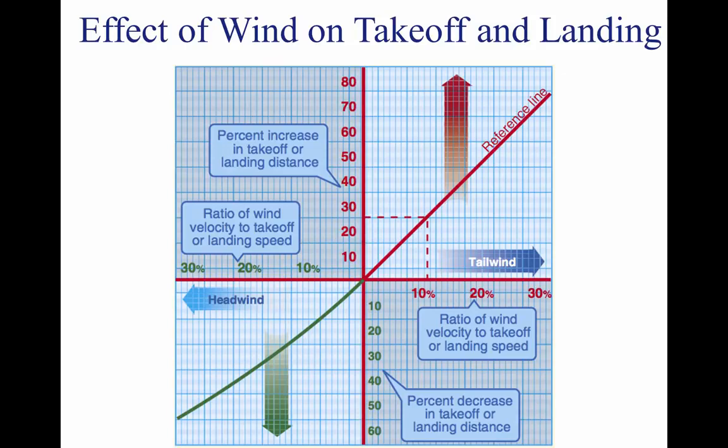Takeoff performance. The minimum takeoff distance is of primary interest in the operation of any aircraft because it defines the runway requirements. The minimum takeoff distance is obtained by taking off at some minimum safe speed that allows sufficient margin above stall and provides satisfactory control and initial rate of climb. To obtain minimum takeoff distance at the specified liftoff speed, the forces that act on the aircraft must provide the maximum acceleration during the takeoff roll.